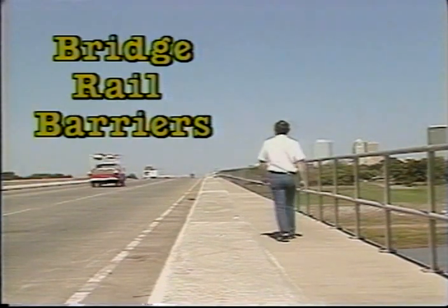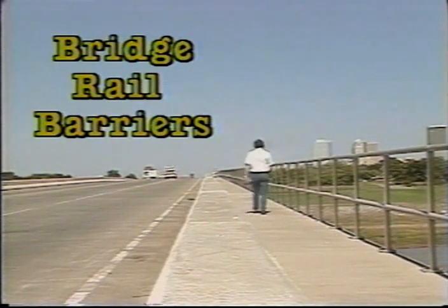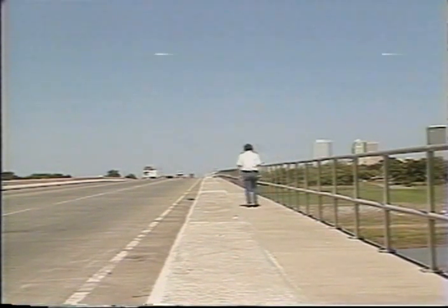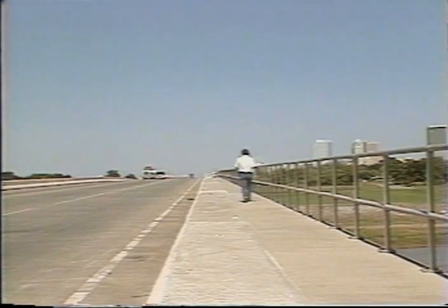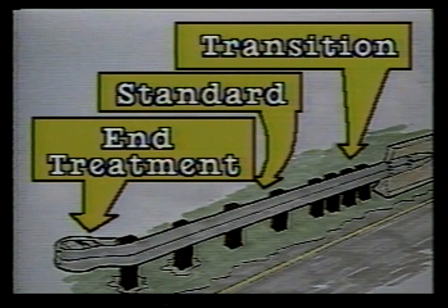Bridge rail barriers provide protection from one side only and are used to keep the vehicle from going off the bridge. They may be used occasionally to protect pedestrians from vehicular traffic. Traffic barriers are classified according to their stiffness. They're identified as flexible, semi-flexible, or rigid systems. Traffic barriers have 3 parts, each designed to do a different job. These parts are the end section, the standard section, and the transition section.